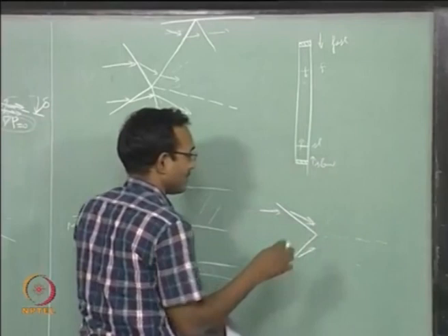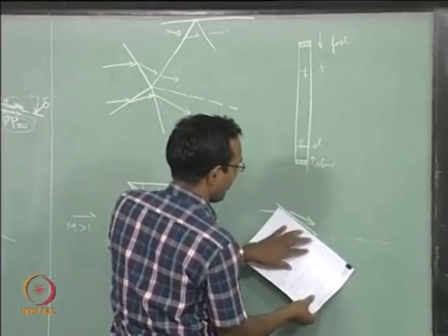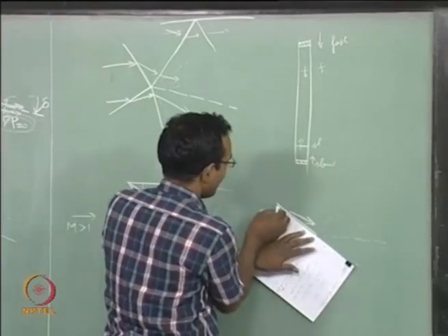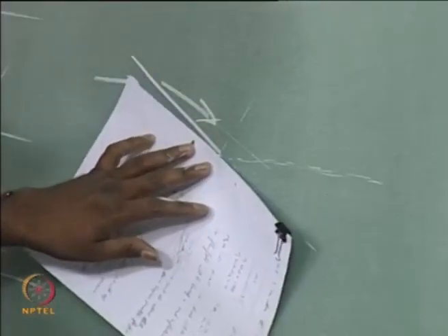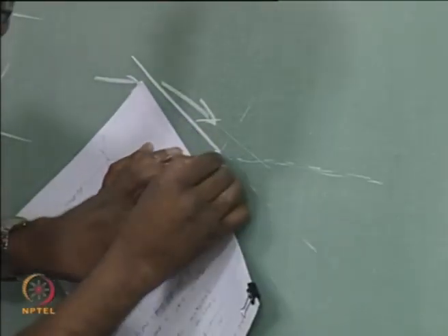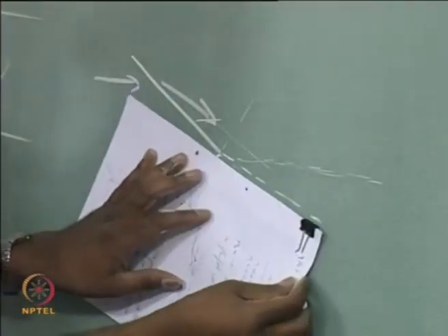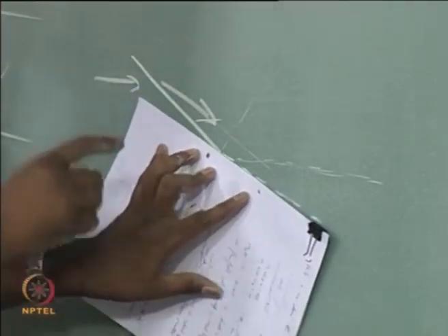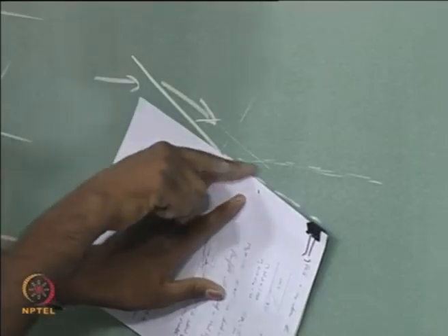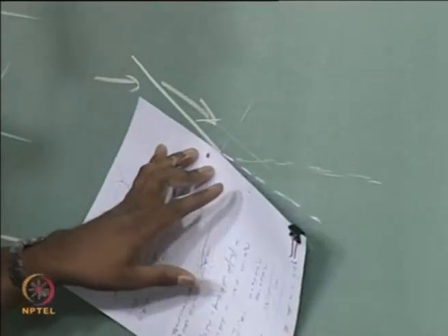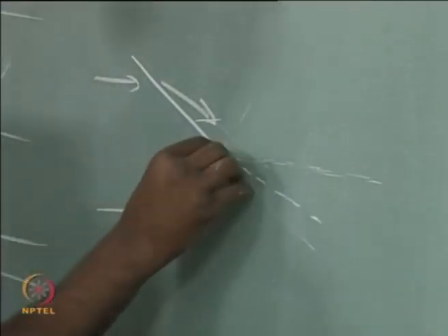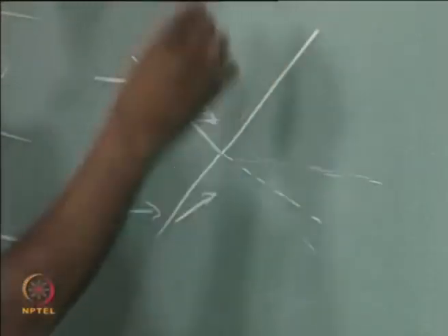How do we look at this as an oblique shock problem? I will block this particular part like what we did last class. The flow is supposed to come parallel to the streamline, like what we did last class, right. I will draw a line like this, the flow is coming along this paper and then turning to that direction. If that is the case, then there will be an oblique shock sitting somewhere there.